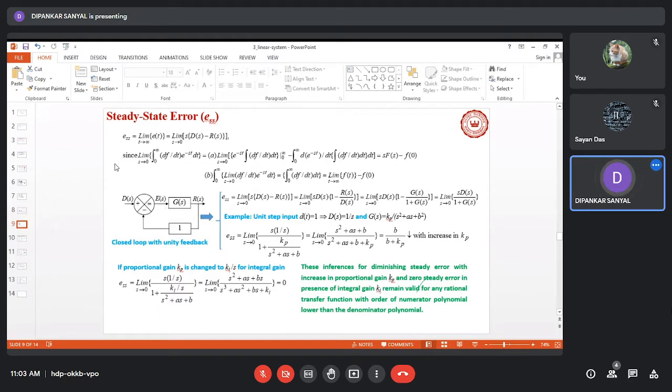So if we excite a system with a sinusoidal input and if the system is stable, what we'll observe is that after a certain time the transients will decay off and we'll have a repetitive sinusoidal oscillation of the same kind. And when we have that same kind of sinusoidal oscillation, though it is not steady in real terms, in control parlance we call that the steady solution.